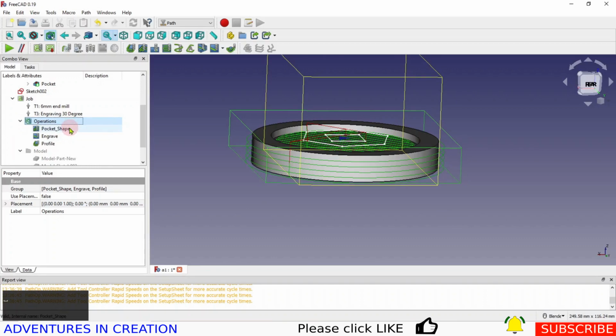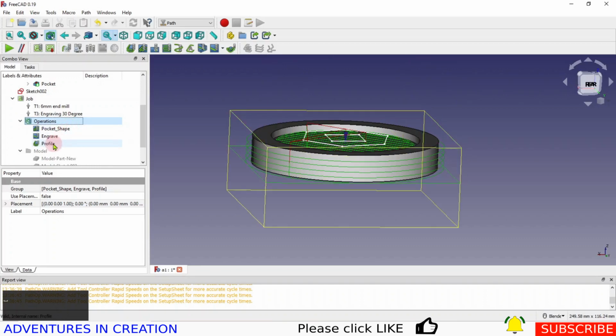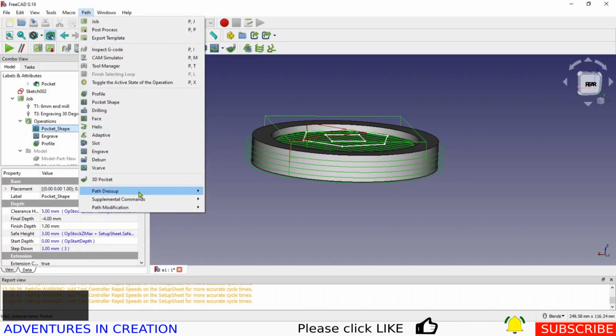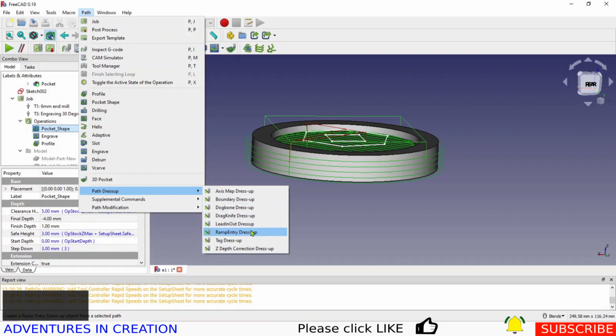So here they are: the pocket shape, that's the first one. The engraving, that's the second one. And then the profile, that's the third one. And basically what we're going to do now is add some additions to that. So for this pocket shape, I want to add a path dress up that is a ramp